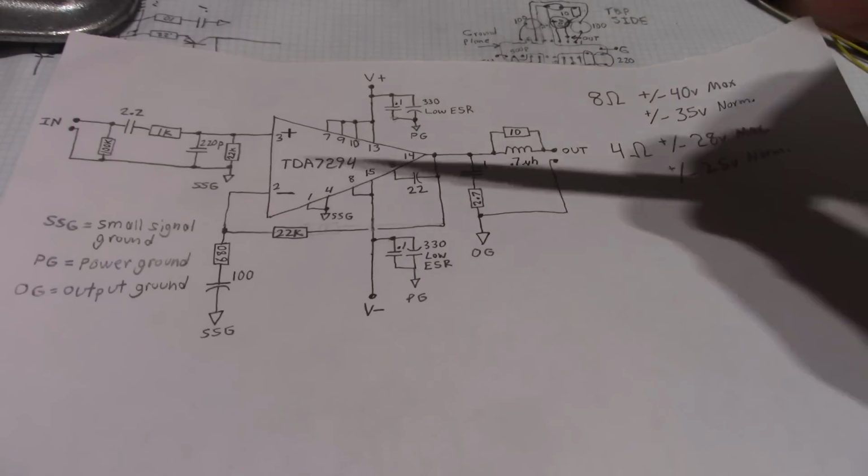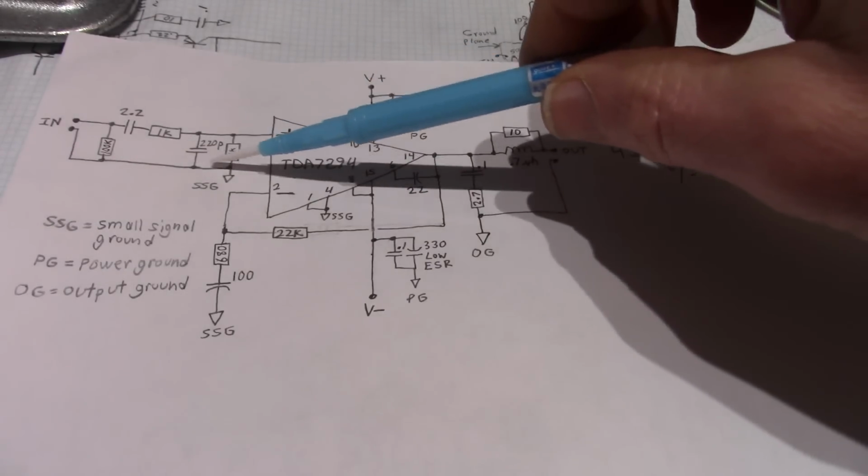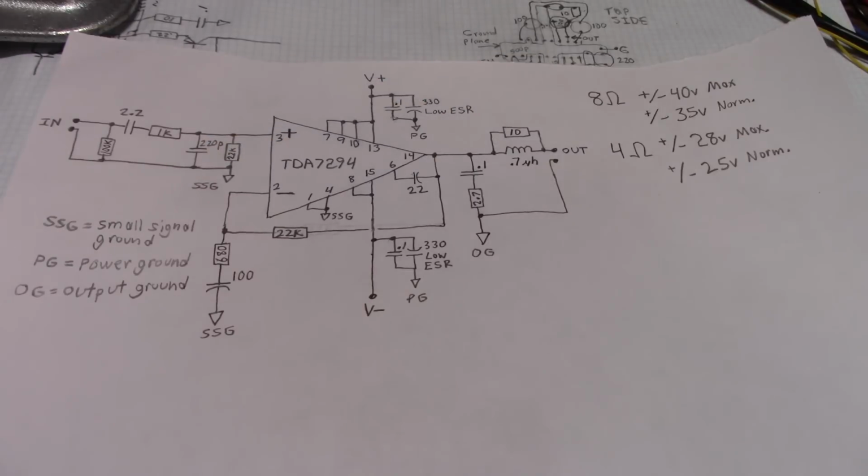For example, if the input's open, you have an RCA jack and you plug a connector in with the amplifier on, well, a fault of the RCA type jack is that the live center conductor makes contact first and you'll get a loud burst of hum. The amplifier could even feed back on itself and oscillate, and that will potentially damage the chip. So I recommend having a low pass filter to help prevent that oscillation.